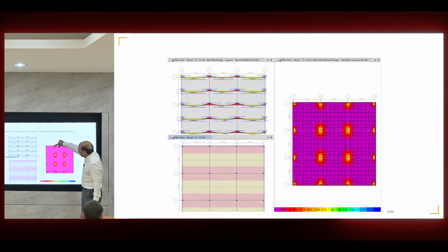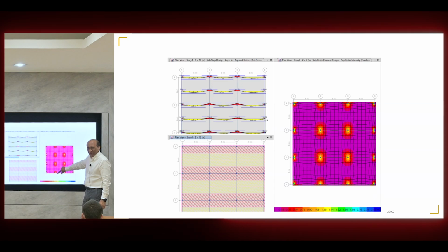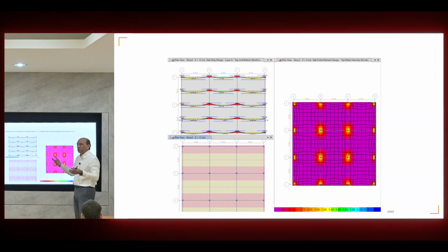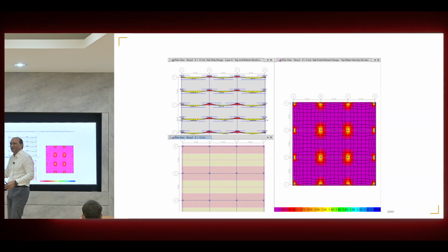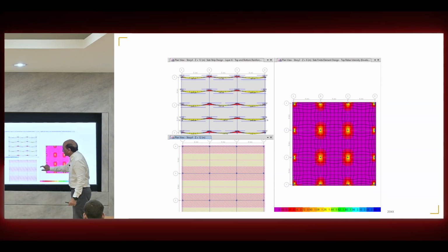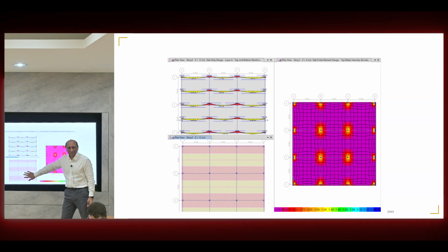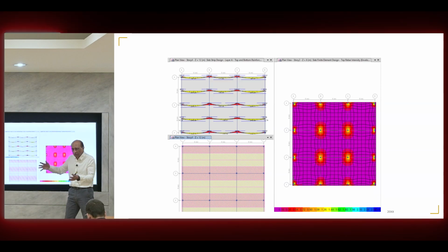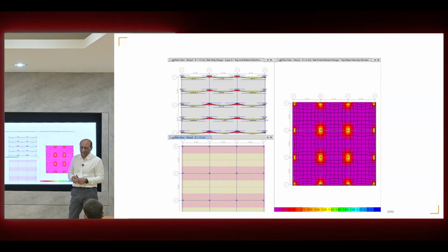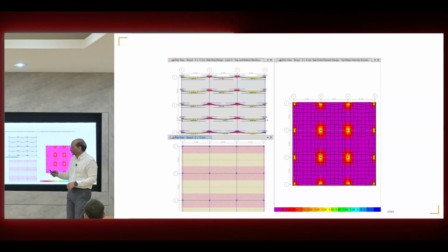So this portion has a different reinforcement, and this portion has a different reinforcement. It is determined on the concept of design strip. It is similar to what people used to do, slab reinforcement transferring to beam. So now we think of these strips as support strips, and these strips as supported strips. So column strips, middle strips. And there's a whole rule and logic on their size and everything. We'll talk about that when we come to the design. But that's where we are moving to.